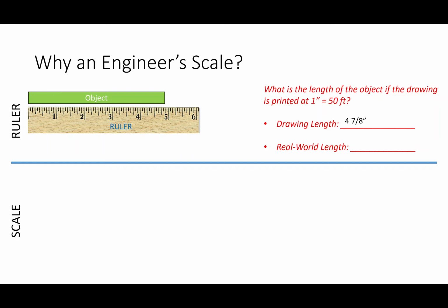Sure. Yeah. So in order to determine its length in the real world, I have to break out my calculator, because I say, okay, 1 inch equals 50 feet, and the drawing is 4 7/8 inches. So 4 7/8 times 50 is about 244 feet. So I have to use a ruler in combination with a calculator.